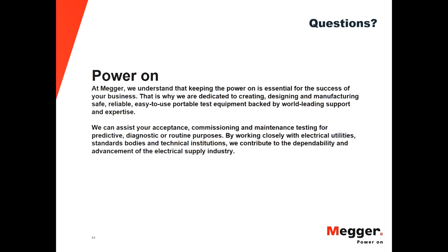So yes, the battery charger is supposedly capable of carrying the entire load of the substation, and that's what it actually does under normal operation. The charger is supplying the load, and it's supplying a little bit more so it can maintain the charge on the battery. So that's what the floating condition is: it will supply voltage and current for the load and the battery at the same time.